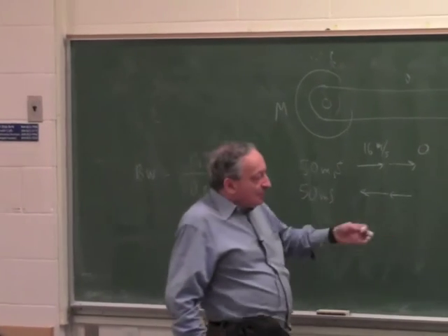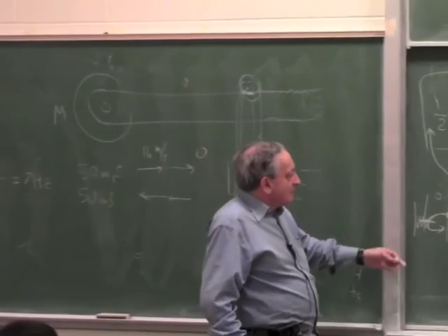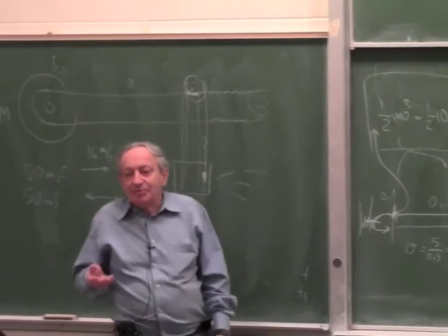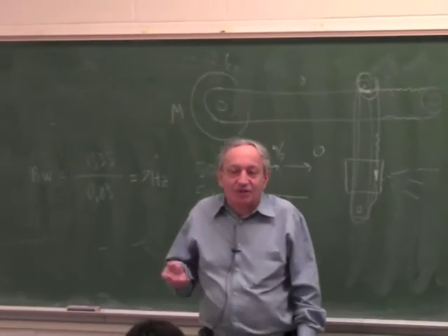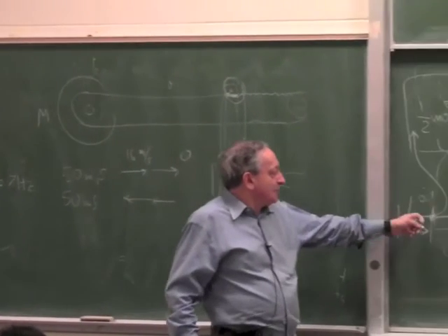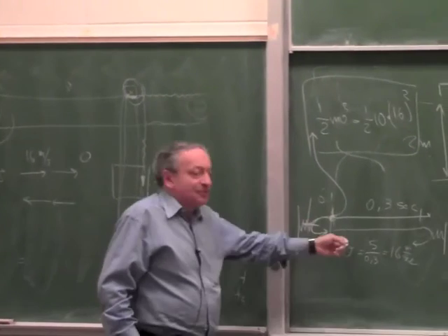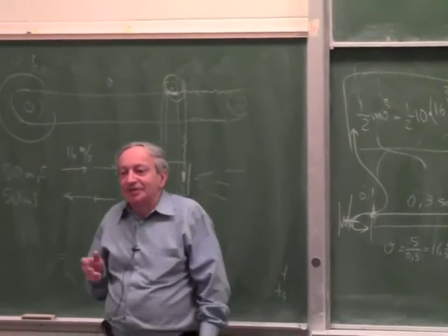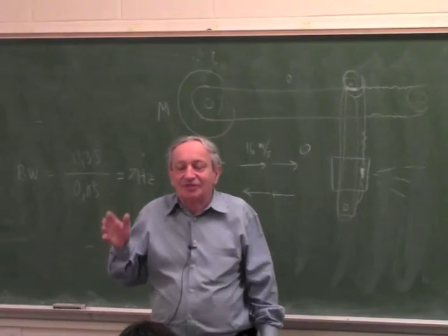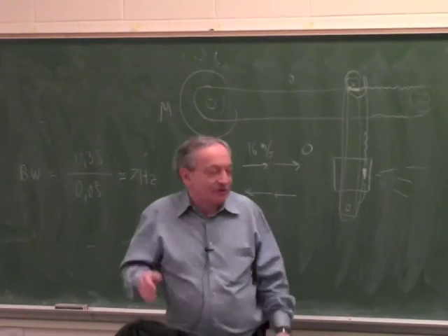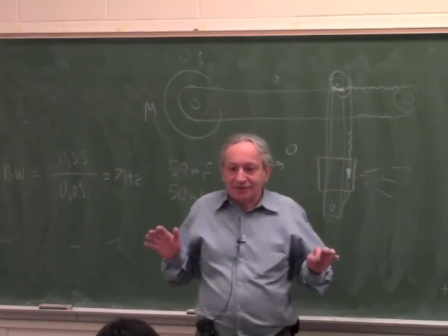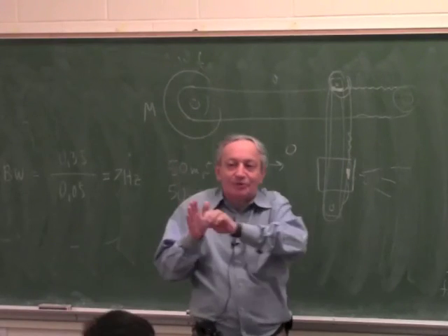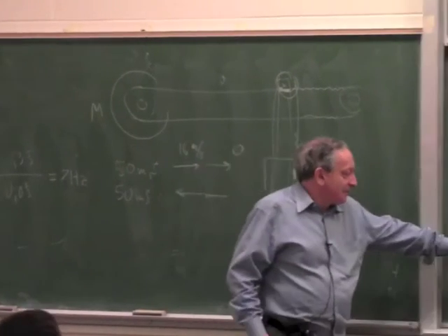There is actually a simple way to do regenerative braking. So the power you need is just maybe 20% of the energy. We said the energy here, you have to dissipate 1300 joule and then input 1300 joule. But if you have some kind of a spring or a bumper, maybe you assume 20% of that would be enough. Because if it was frictionless, you would need 0. Because frictionless, the spring will absorb all the energy at the end of the travel and output it all back, come back to this velocity.